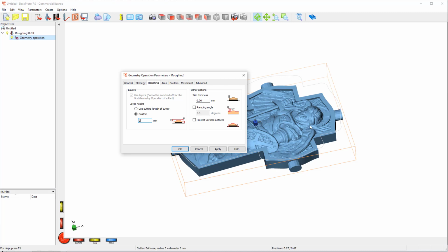What we're doing with the roughing pass is removing as much of the material as possible with the big tool that can do it easily, so that when we go in with the small tool, we don't have to struggle with all these lengths over here. We can go in and do a final cut right down to the bone. It means the smaller tool can move a lot faster without risking breaking. So I'm going to put in, I guess, say 0.3 millimeter skin inside there.